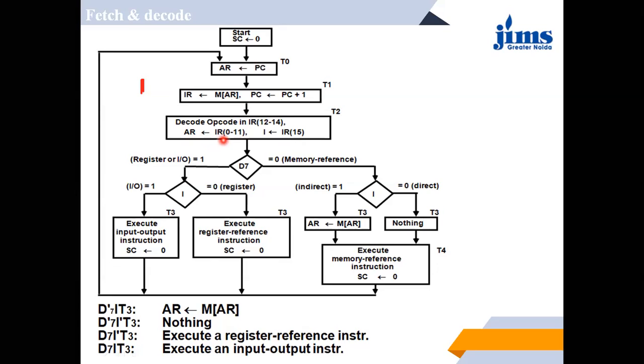The mode bit, the MSB of the instruction register, is 1, and bits 12 to 14, the 3 bits, are for the opcode, that is, the operation to be performed.